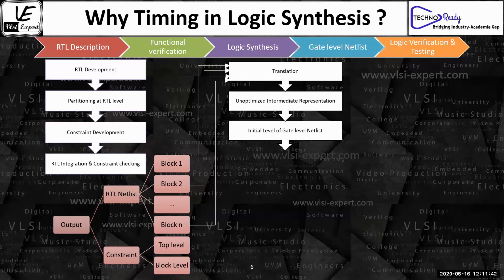Logic synthesis is a place where we convert my RTL, which is like an A dot B, and just map it with the technology library also. Because if you remember, just a few seconds back, I mentioned the standard cell library. When I'm talking about a particular technology node, there is a standard cell library. That means now you know the physical structure, the physical layout, you know the timing, you know the power, you know the area, everything you know about that AND gate.